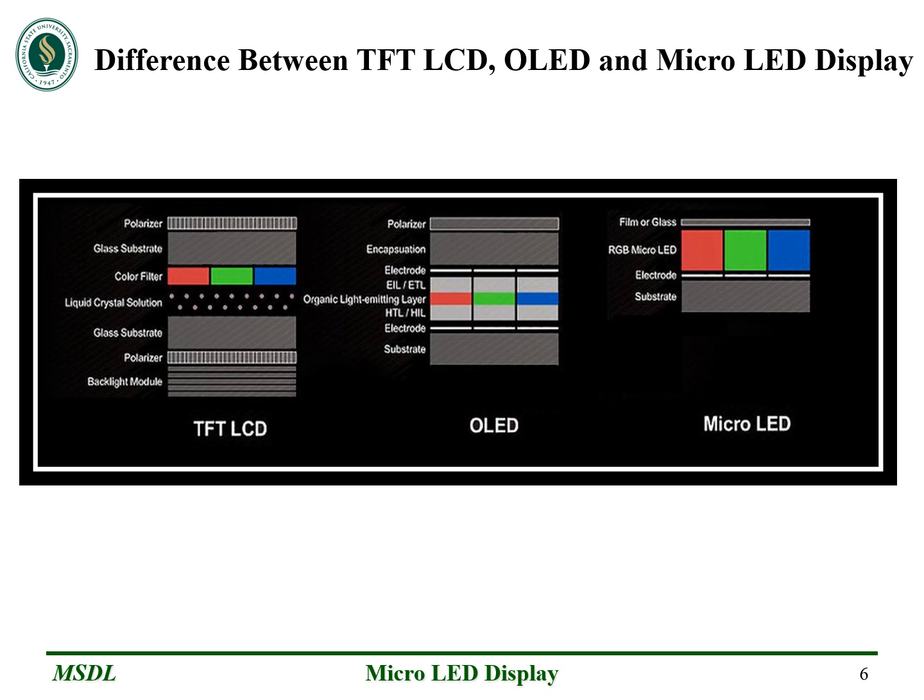In the OLED, it is triggered by electric current. OLED can emit light in various colors by mixing the red, blue, and green light from its organic thin film, which is more vivid than a common LCD screen. Micro LED features miniature LED arrays, with each micro LED functioning as a pixel and can be driven to emit light. With the pixels becoming smaller and brighter, image quality and response speed improve.